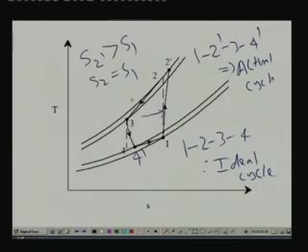So what is the consequence of this difference? You will find that temperature T2 dash will be larger than temperature T2. Because of the irreversibility, you find that the exit temperature is higher compared to the ideal isentropic process. And process 2 to 3, in actual this should have been point 2 should have been here, and the heat rejection should have taken place ideally along a constant pressure line, but you will find that because of fluid friction there is a pressure drop here,